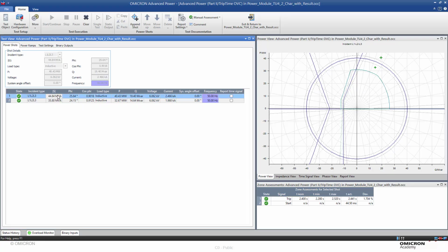here. We can define some shots, as you can see above and below the characteristic, which is the overcurrent protection characteristic. And you see this point now is no any trip expected, but in the point number 1 here we are expecting the trip, and here is the actual tripping based on the overcurrent protection setting in the Siemens relay.